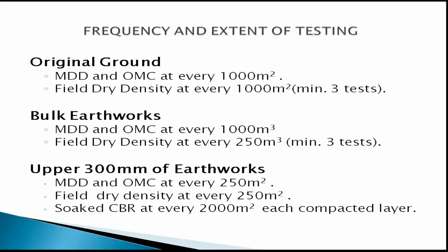For the upper 300 millimeter of earthworks, the materials that we have brought from the borrow pit are laid and compacted. And for an area of 250 meters squared, we need to pick samples and do the laboratory compaction test to determine the MDD and then the OMC.